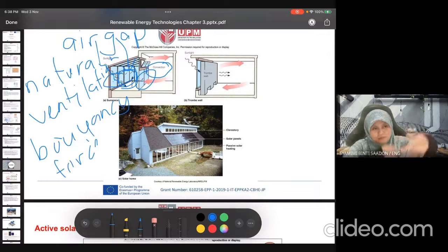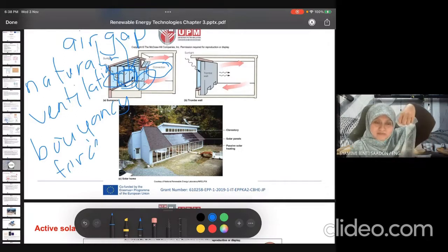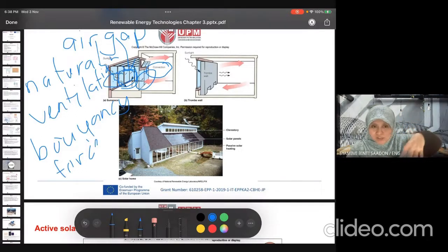So in the air gap, the fluid will flow, we assume the hotter one will go up, the colder one will go down. So it uses this theory, to apply in the air gap of double glazing, the two glazes, without any ventilation force. Just naturally, the air. So we assume that is why this type of design, the sun space design, is used a lot in countries which have 4 seasons, like they have winter, for example, right?